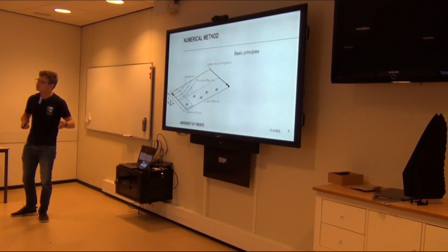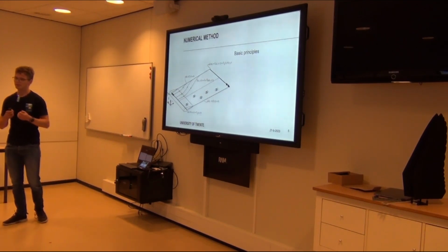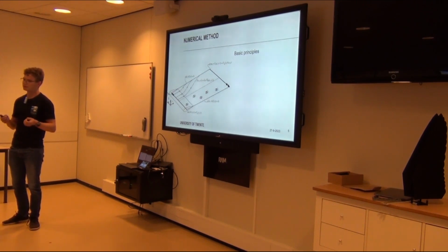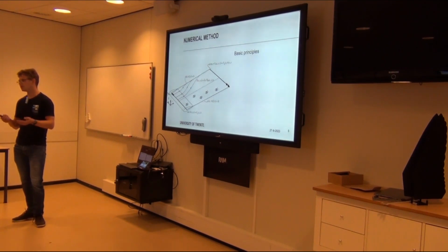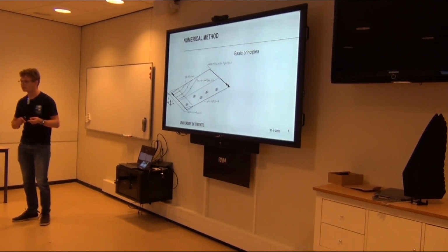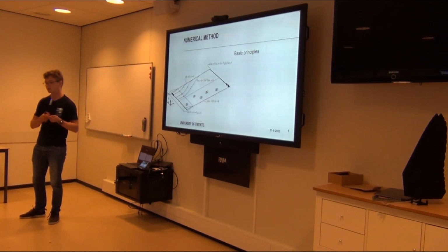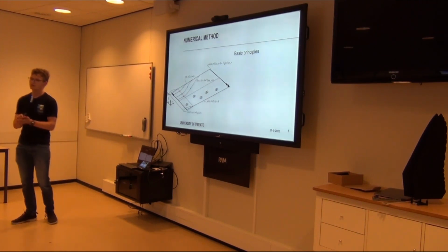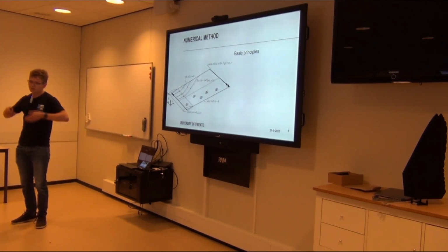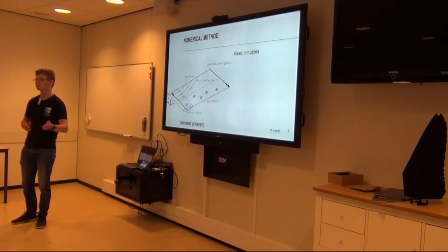What we did is we made a very basic numerical model with potential flow theory. If you're not familiar, the philosophy of potential flow theory is that you make some assumptions about your flow, such as inviscid flow and incompressible flow, but most importantly, irrotational flow. That allows you to squeeze certain flow phenomena. It really allows you to squeeze your vorticity field and your source and mass flows to singular sources. So lines, points, what have you.